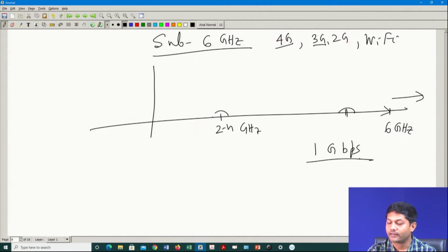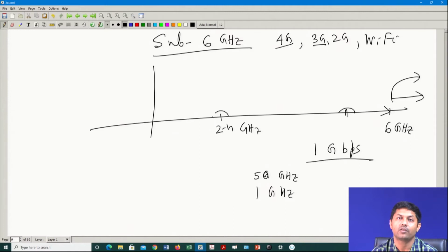The second part of the story is that most of the components that are available today are tuned for 6G or those kind of things. Now, even if you suddenly increase the RF and say okay, I am going for say 50 gigahertz RF, there I can say I am taking 1 gigahertz spectrum. Does it solve my problem? No, it does not solve your problem. It actually comes with a lot of other problems.